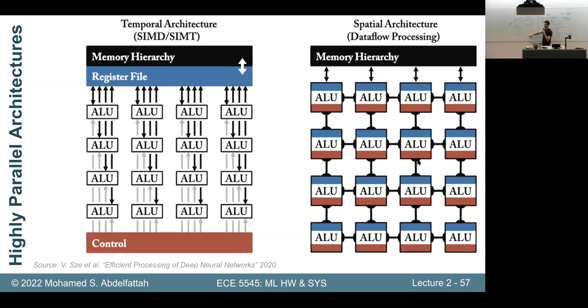FPGAs and ASICs come into play because you really sometimes do need to go to this multiple instruction, single data paradigm. So examples of applications that really need this are things like compression and encryption, and things that need high throughput, but at the same time have complex control flow and dependencies, which can be resolved this way.